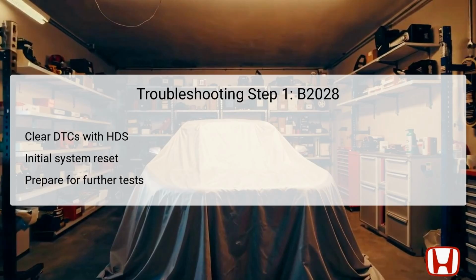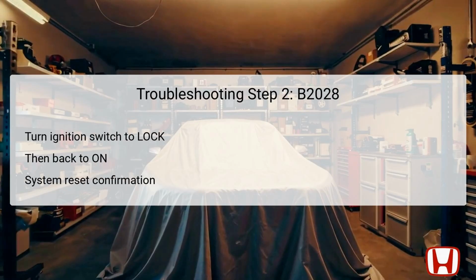A successful reset can eliminate any minor glitches that may not reflect deeper issues, ensuring that the technician focuses on genuine concerns. Effective use of the HDS is essential in modern automotive diagnostics, requiring both skill and familiarity with its functionalities. Once the DTCs have been cleared, the next step requires turning the ignition switch to the lock position before turning it back to the on position. This action is important as it serves to reset the ignition system, ensuring all electrical components are functioning correctly.